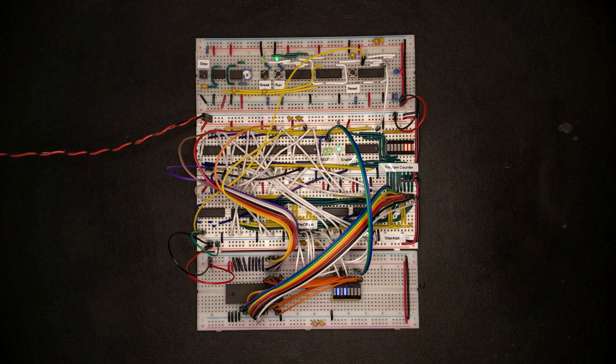Awesome. Our CPU recognizes a few rudimentary instructions and knows how to execute them. And we have a handy flash memory that we can load the program into. However, we're limited to 4 bits of jump addresses and offsets, and we're already using 6 out of the 8 total number of bits in the instruction just to be able to jump around the program. We're not even doing any real work yet.